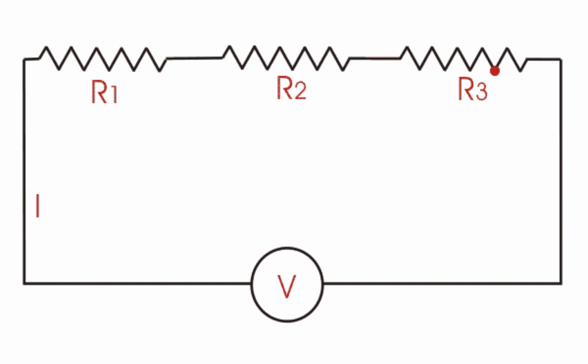Voltage drop in a series circuit. Voltage is the force that pushes the electrons through a resistance. The amount of voltage required is determined by the amount of current flow and resistance. If a voltmeter is connected across a resistor, the amount of voltage necessary to push the current through that resistor will be indicated by the meter. This amount is known as voltage drop. It is similar to the pressure drop in a water system.